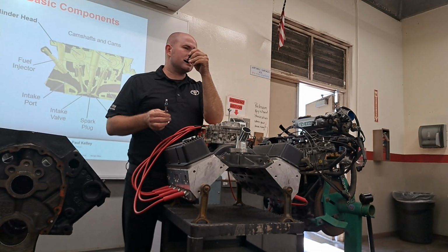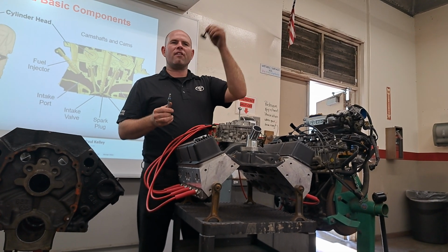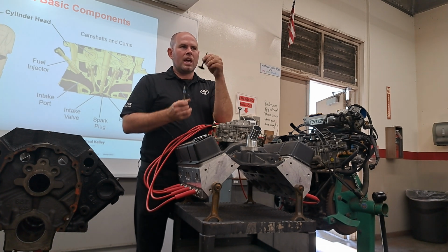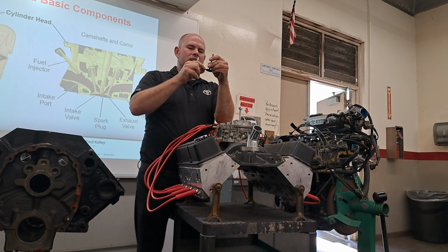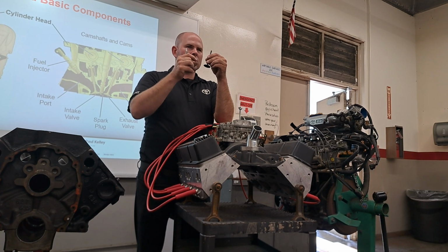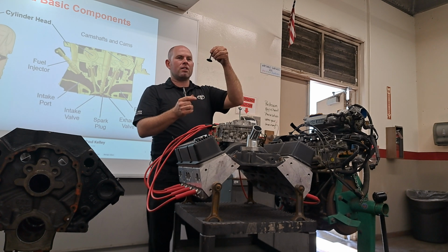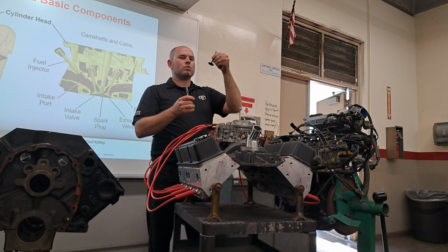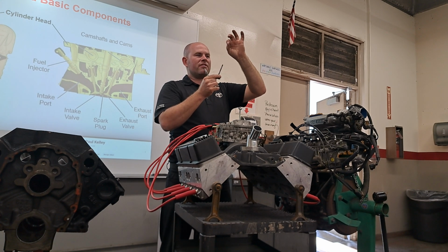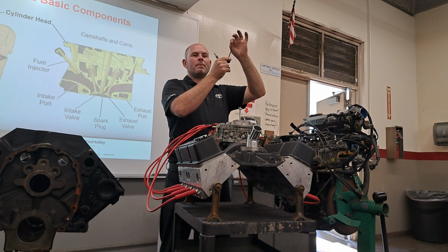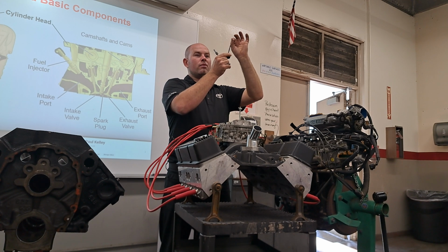For longevity though, the valve spring has slammed this valve closed like a bajillion times. And every time it does, it slaps up into the head. And the problem is that titanium's kind of soft, so it wears and wears and wears. Now think about it. Your valve is slapping up into the head, right? So over time, it beats its way further and further up. Remember, you got a cam up here. As the valve gets further in the head, what do you think happens to that 7 thousandths of clearance? 6, 5, 4, 3, right?